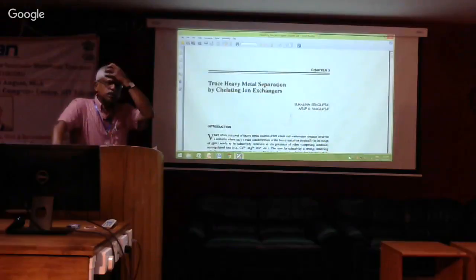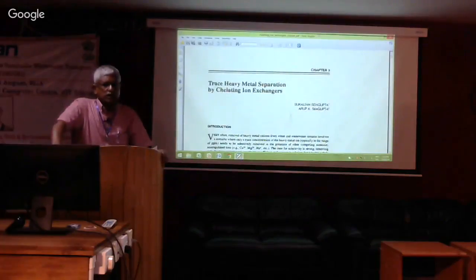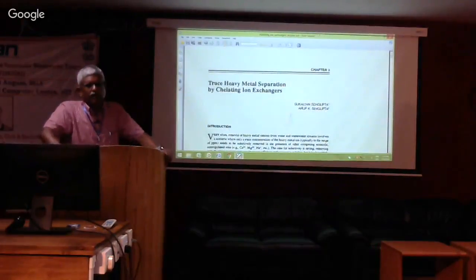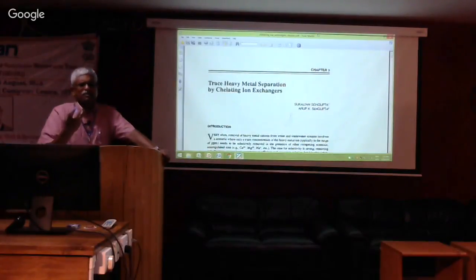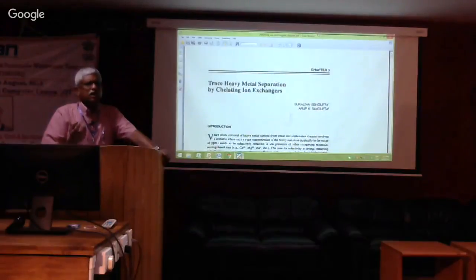But more than suspended solids, what we found is there are some other contaminants in the water. We don't really have a full idea of their composition, which I think are organics. These are fouling the zeolite. So the zeolite turns a very blackish, brownish color, and no matter how many times you regenerate, that color doesn't go away.